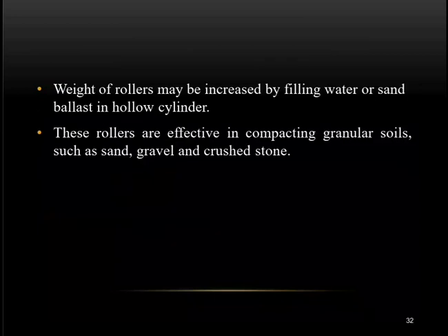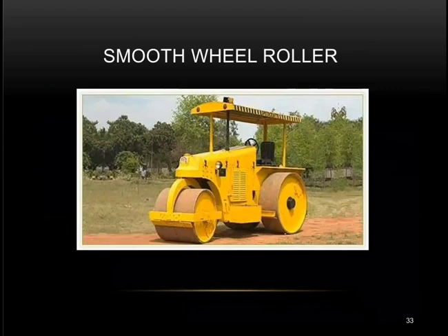Weight of rollers may be increased by filling water or sand ballast in the hollow cylinder. These rollers are effective in compacting granular soil such as sand, gravel and crushed stone. So here you can see the image of smooth wheel roller.